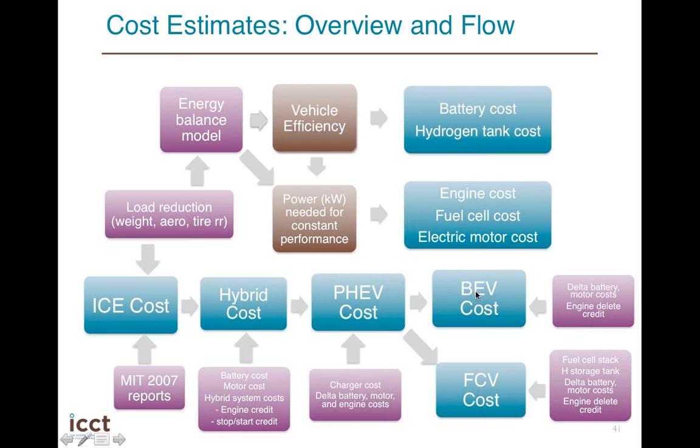From the plug-in hybrid, you move to the battery electric, which again, more assessment of the change in the cost of the battery and the motors. Now, you also get to completely delete the engine, which is a big credit. And then for fuel cells, it's similar to the battery electric, except of course you have to assess the cost of the fuel cell stack and the hydrogen storage tank. So this is an overview of how we went about assessing the cost.